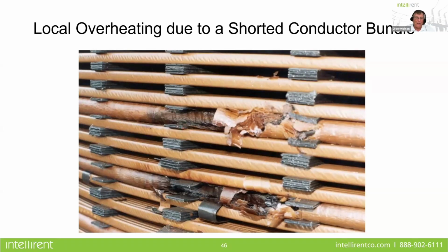And since you're doing a leakage reactance test and a lot of your modern test equipment has variable frequency voltage in the power supply, I would highly recommend to incorporate and interrogate this as part of your routine testing as well. It doesn't take much time, takes very little time. You won't even notice it because you're already connected to the transformer and running the short circuit impedance either way.